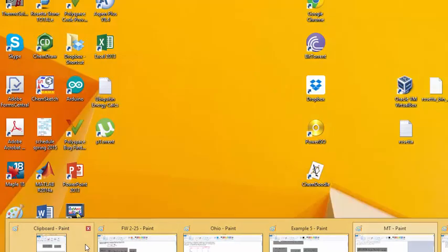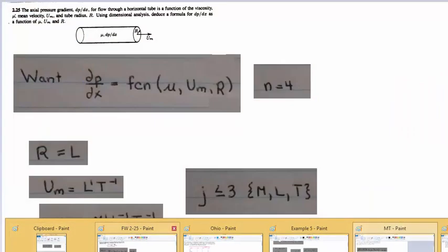Why? When you think about n, which is defined to be the number of blades, that's already dimensionless, because just having, say, 5 of something doesn't have any dimension. Same thing over here, we're given the ratio of 2 lengths. So that's already dimensionless as well, because it would be length over length, which just gets you 1. So that doesn't have any dimension. Regardless, we still have 3 different dimensions going on here. We have mass, length, and time, so our j is less than or equal to 3.